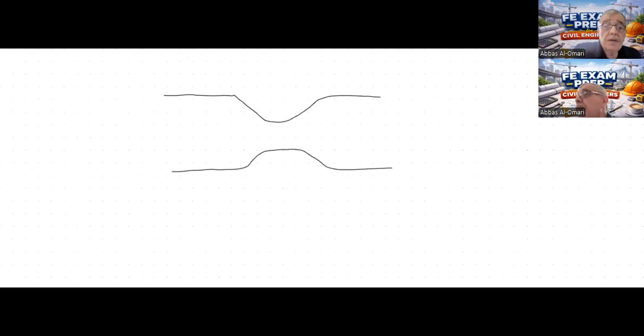So a venturi meter is something like a pipe, and there is a reduction in the area, which is called the throat here. This is the full section, section 1, for example, and section 2 is the throat, where there is a reduction in the area. Now, this reduction causes a pressure drop because as the cross-sectional area reduces, the velocity increases, and consequently the pressure drops. So by measuring the pressure drop, we can determine the flow in the venturi meter.